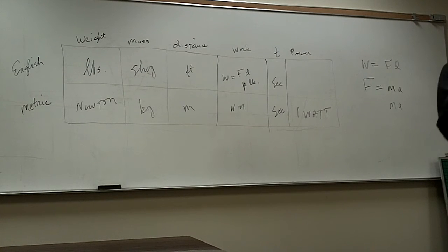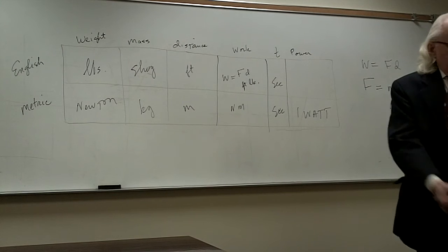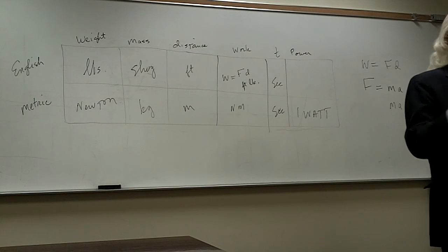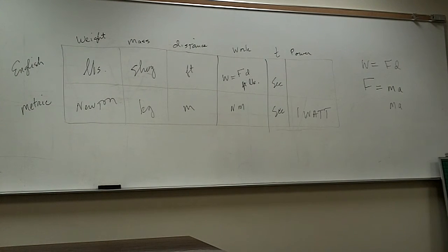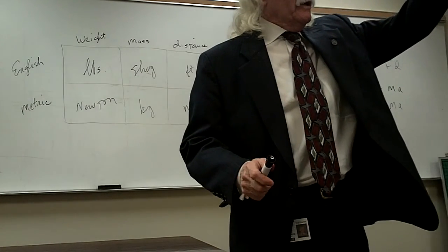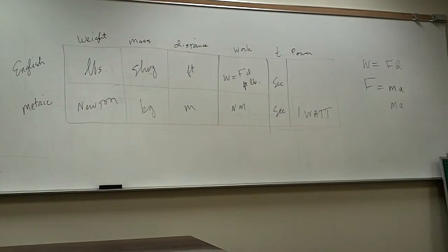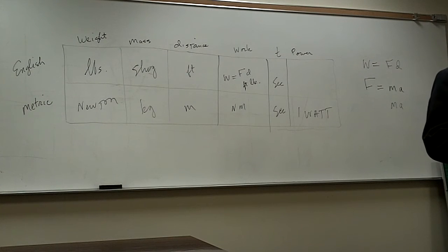You start to get it faster and faster and faster. It starts to oppose you more and more and more. It's called the Lenz's law effect. It's operating against you. So all of a sudden you find yourself twisting it until you get a little tiny flashlight of 1 milliwatt to light up. About the time you feel like your arm's about to fall off, you have lit the light bulb. And you realize how much work it took to make that little milliwatt of power.